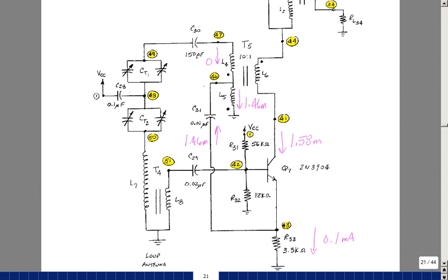Okay, now as time begins to increase, because current is coming out of this dot, it wants to come into here and get larger. So it wants to increase this number. The current that goes down in here is fairly constant, and so the excess comes back here. Some of it starts to split off back this way and then back this way. And so we'll begin to see a decrease in the current that's here. And that's going to be my next point. I'll call that T3, which was the black dot. Let me just erase this again and write down what happened next.